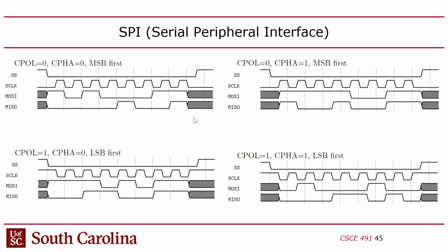So from the software perspective, you're going to do a programmed I/O write in software. You're going to write a control register in software. So software is going to do a store instruction into the hardware SPI controller, and then the hardware SPI controller is going to do all this stuff for you. So that way, you don't have to burden the CPU with trying to synchronize to a clock, right? Does it make sense?